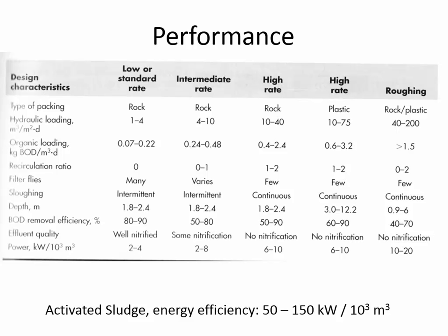the range of performance that you get from different configurations. And a roughing filter is one where it's just being used to kind of take the edge off of the waste, just to reduce the BOD before the water goes into another treatment process. And so on the right side of this table, a roughing filter is one that we don't expect to have a lot of removal.